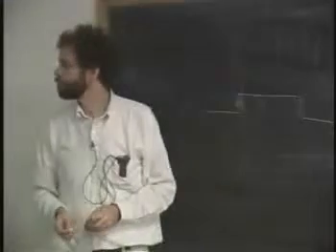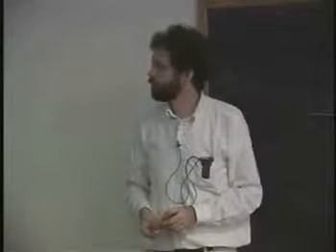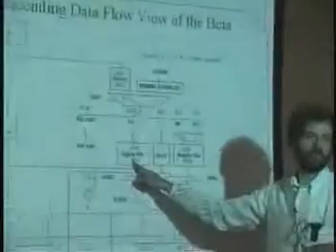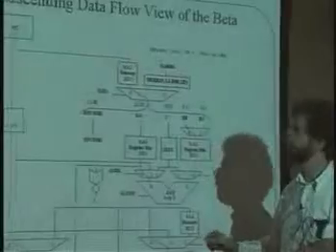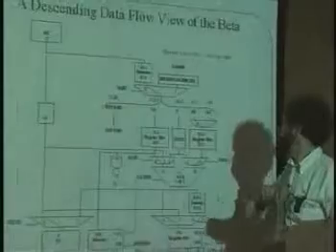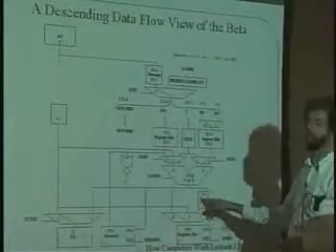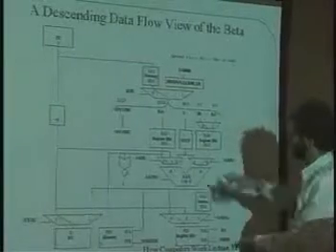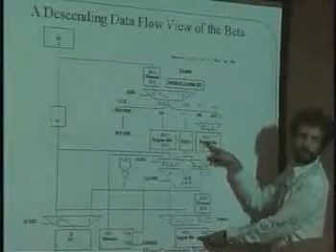The box in the lower right-hand corner named register file, what is that register file? It is the register file with the 32 registers in it. And so this is a port on the same register file that we have this one and this one here. So 2 read ports and 1 write port. And the big slow memory has a write port here, a read port here, and a read port here. Also the same, 2 read ports and 1 write port. So even though they're shown here as 3 boxes, 1, 2, 3, it's actually one system.